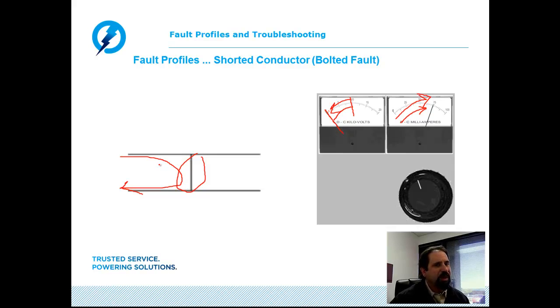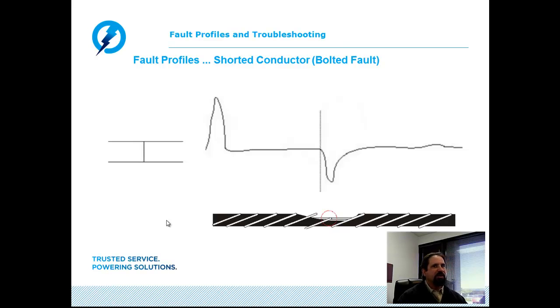So the problem that we face with these bolted faults or short circuits is we could be walking, looking, and listening for this arcing event to be taking place, and it's not going to happen because what we have is a constant current loop going on. Now, if we were using the pulse echo or time-domain reflectometry techniques, one clue that we would have a bolted fault is when we apply the low voltage of the pulse echo, we actually see the fault without ever applying any high voltage.